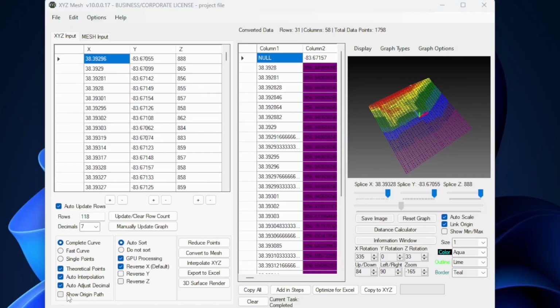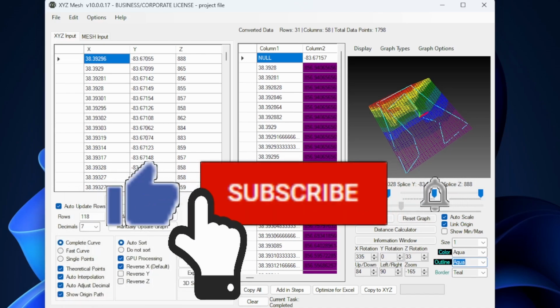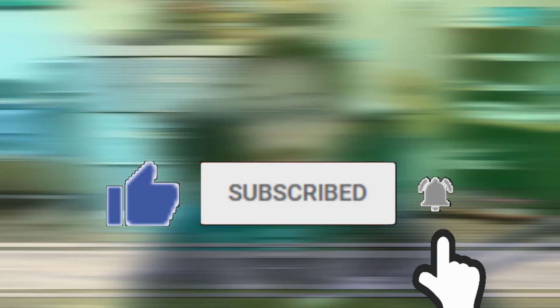This option allows you to change the default color of the original path. The original path option is one that we covered in the previous video, which will overlay the original input data over top of your mesh conversion. This option will also change the color of the points selected from the Select Points options, something we'll cover in another video.